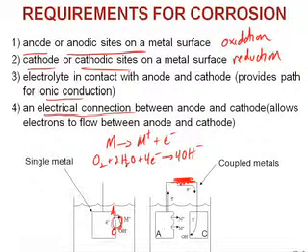Here we have two metal surfaces. This is galvanic corrosion, when we have two different metals that are in contact. I'll talk about this later. But these anodes and cathodes can be on a single metal surface, and if they move around the surface, we end up with general corrosion, eventually eating up that whole surface, and the thing dissolves away, which is what happens when we immerse that zinc into the acid.